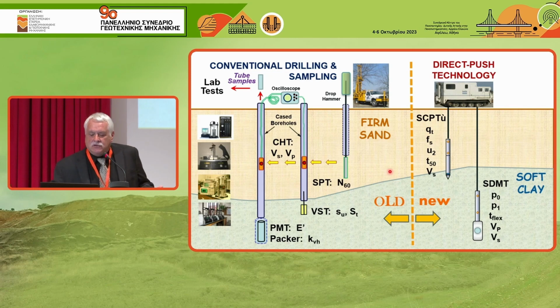However, I still work more on small projects, medium projects. I still need numbers to keep me out of lawsuits, to keep the lawyers away, so I can do my job properly. So I'm recommending the seismic piezo cone with a seismic dilatometer because I can get 5 readings with depth from the same sounding.